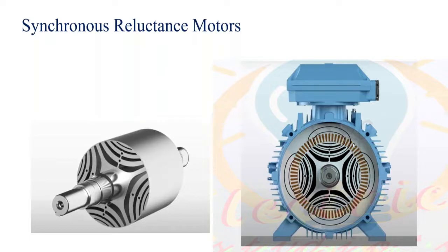The advantage is that I don't use any windings. The absence of windings gives a lot of advantage, but the main problem is the saliency ratio. Because of that, I am not able to develop the torque needed for an electric vehicle. This is what people were telling, people were blaming like this.